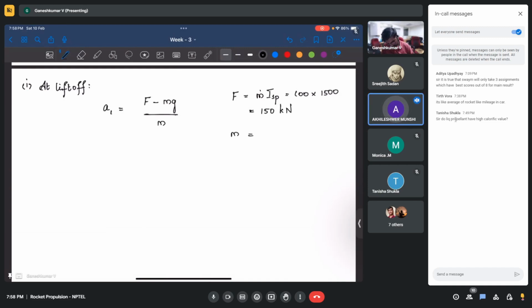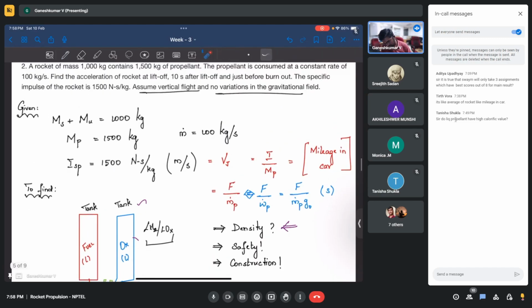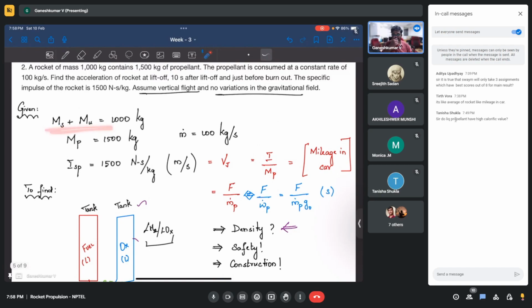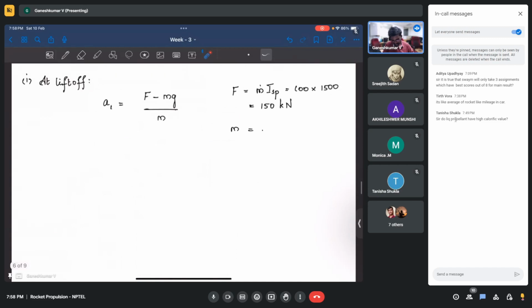Okay. Now, what is the mass at liftoff? 2500 kg, assuming no payload, structural plus the propellant. Actually, what we considered was the rocket mass we gave, so we added 1000 kg, which includes payload. If payload and structure are included together, that is 1000 kg, plus at liftoff you have all the propellant loaded, so plus 1500. So it's going to be 2500.